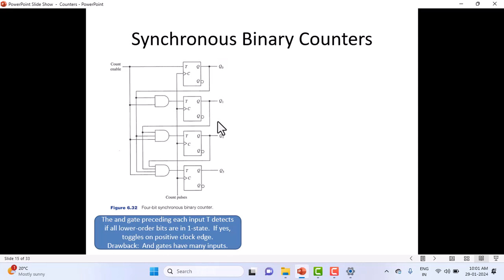This situation will come across in system design. Look at the laptop. Don't you think that every gate needs many more ICs? Your processor needs to drive hundreds of ICs. How are you going to overcome that fan-out problem in the case of laptops? Using buffers. Have you come across buffers? Buffers will amplify, they will boost the levels. That's why you see in computer design, in processor design, every output we connect what is called a buffer.